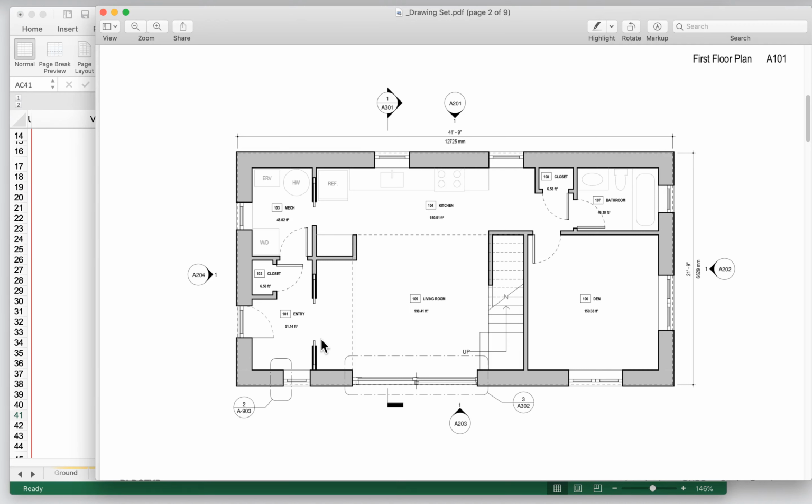You could maybe make the argument for this window over here, but not really. It's assuming this door is open. It's really around the corner here. I'm going to say that these windows do not have cross ventilation, assuming that we don't leave this door open all day, every day. If we had good robust screens, or a screen porch here, maybe we could leave this door open, and then obviously we would get a tremendous amount of air exchange across the main space here.